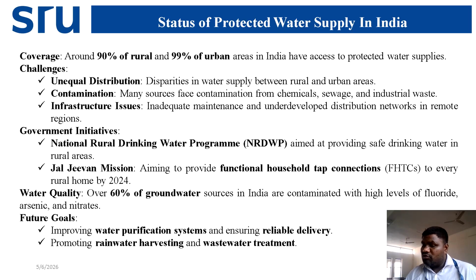See here how to treat. I will tell you the typical wastewater treatment plant. First will be the screening. Here the large objects will be stopped. Then the remaining water will be sent to the next unit, that is a grit chamber. Here maybe inorganic material such as sand particles, maybe some kind of dust particles, will be stopped here and settled at the bottom of the tank.